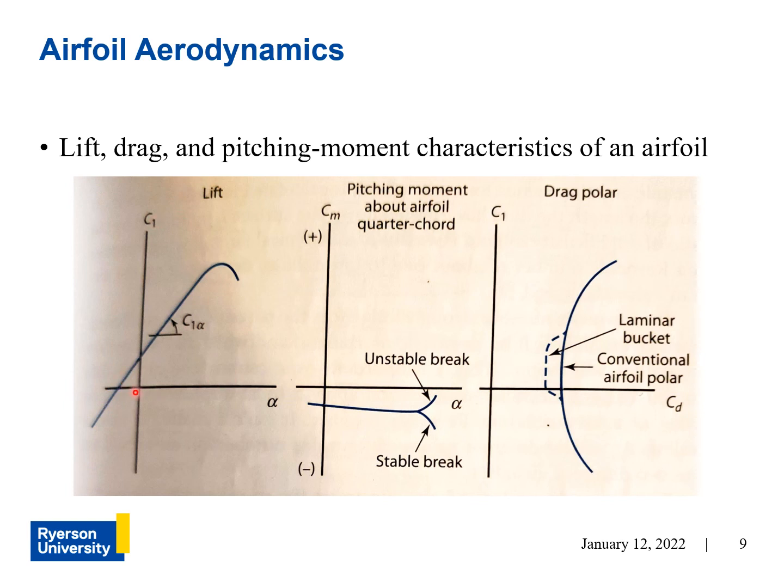And so if you knew the angle of attack of the aircraft, then you'll be able to find the lift coefficient. And once you know the lift coefficient, you can maybe use a ruler and draw a line straight to the drag polar. And at that point, you draw a line straight down to the horizontal axis. And then from that, you'll be able to know the value of the coefficient of drag.